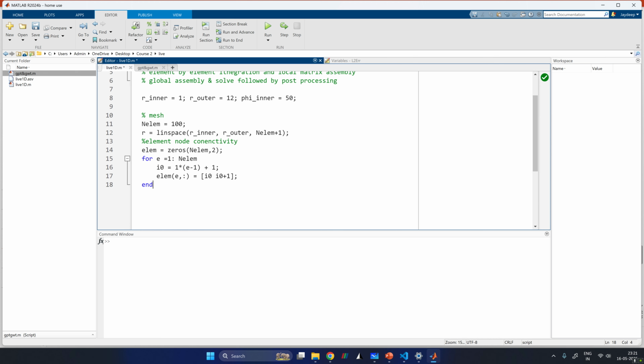Okay, so this is the element to node connectivity list. Whenever I call lm of e, all the rows, if I call lm of 4, then I'll just go to the 4th element and I'll just grab those nodes, right? So you can understand this is very useful in unstructured meshes. You can just grab the nodes from any element even if they are scrambled. So it is really important in those cases. Here it is quite trivial.